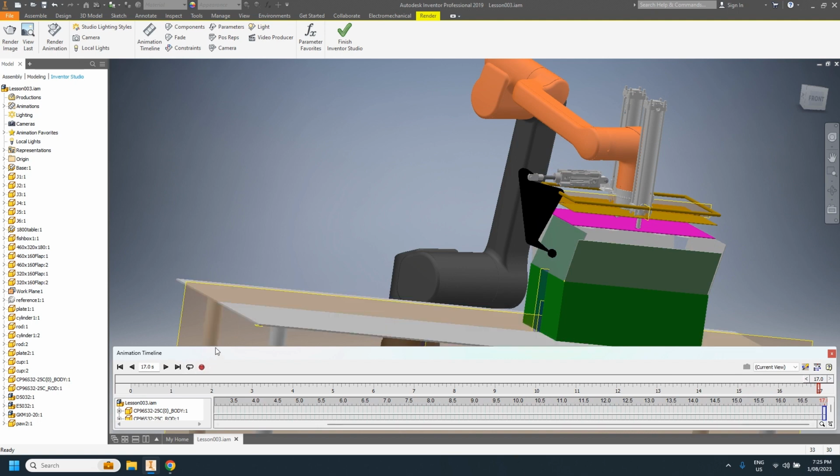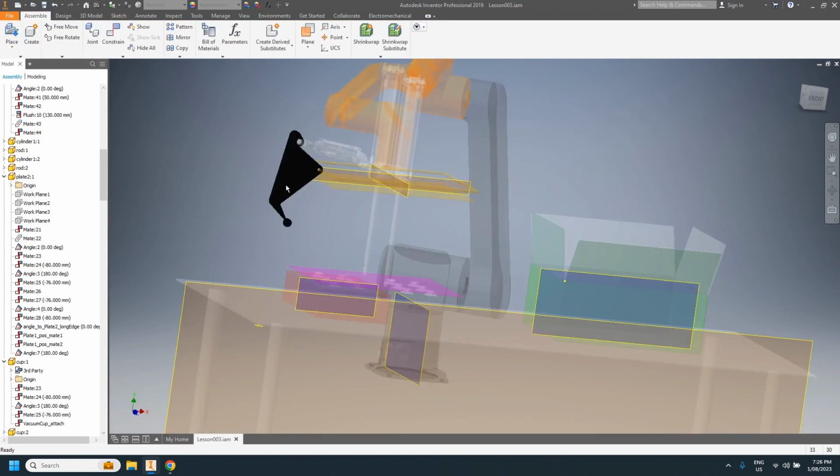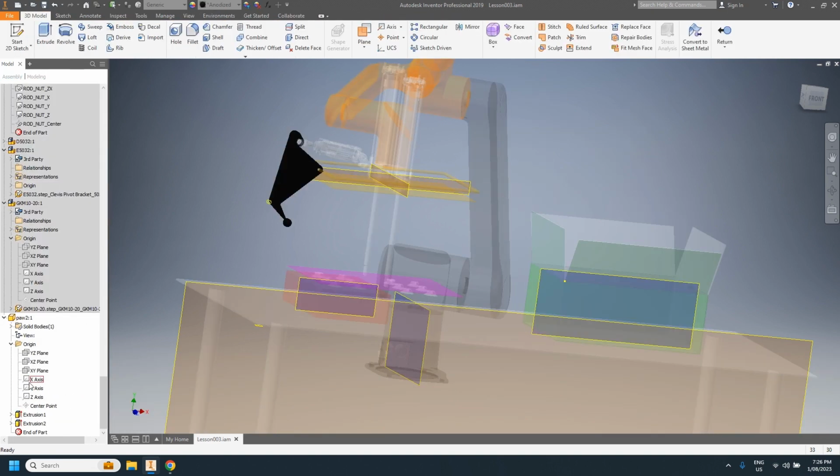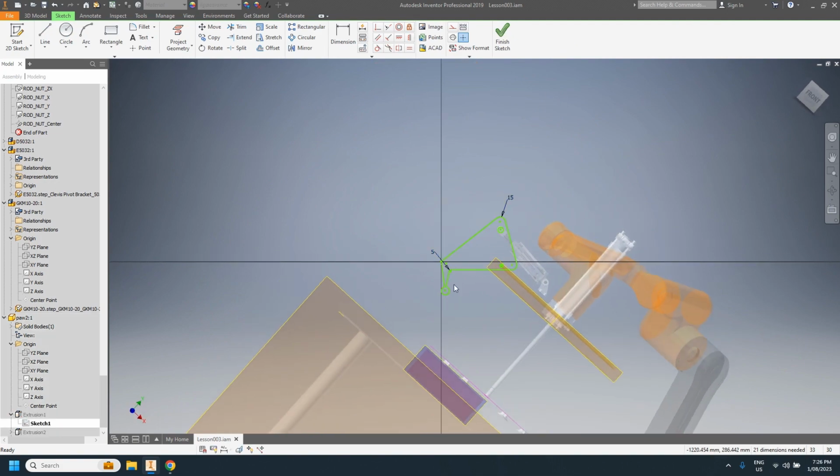Okay, now because the tip is not long enough and low enough, I'm gonna modify this position, and in other words, I will make this geometry a little bit down. So double click, you will do the local editing. This one, double click again to do the 2D sketch.